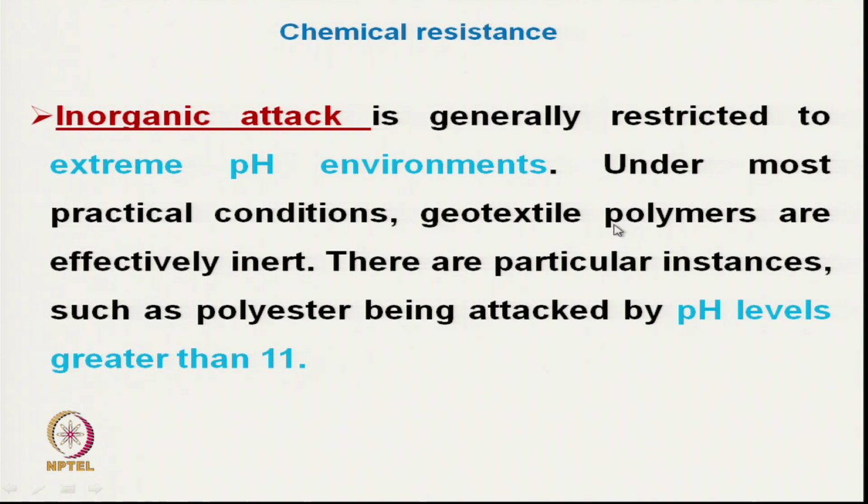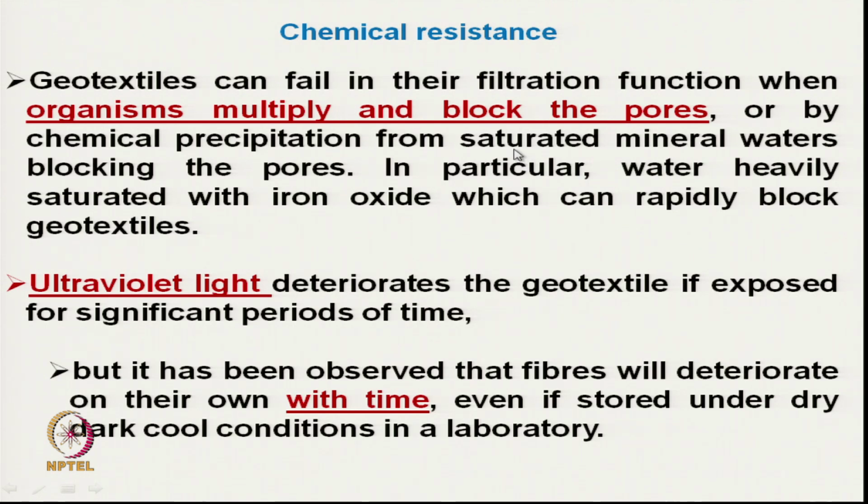We may select the fiber accordingly. So, polyester may be attacked by inorganic chemicals of pH more than 11, and sometimes the organisms may block the pores. Once they enter into the geotextile, they multiply and block the pores.